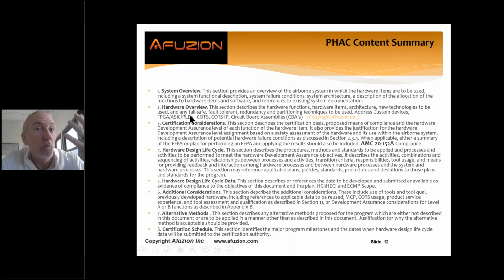Of course, software is always custom unless it's certifiable, RTOS, right? Well, what are those devices? What individual simple and complex devices do I have? What circuit board assemblies do I have? Am I testing those at the hardware level or at the system level? And then certification considerations. What's the basis? Am I applying AMC 25.1309? Am I planning on a FFPA, functional failure path analysis? What's my hardware design lifecycle?